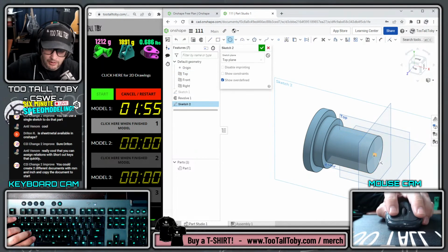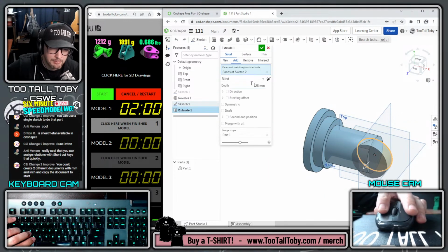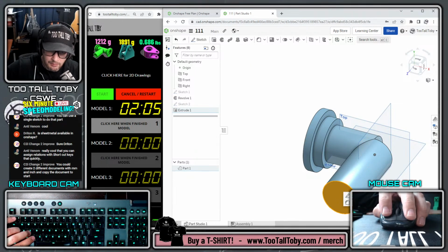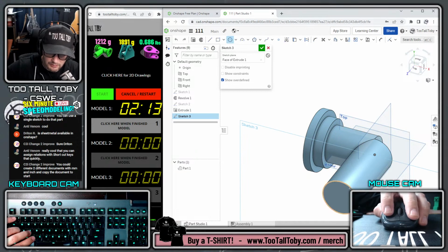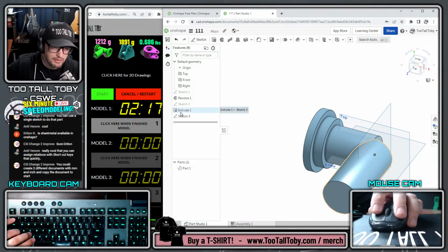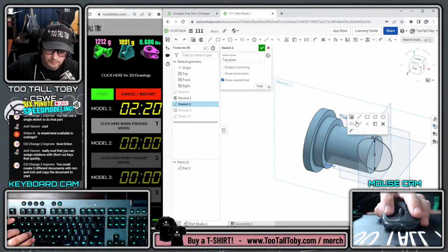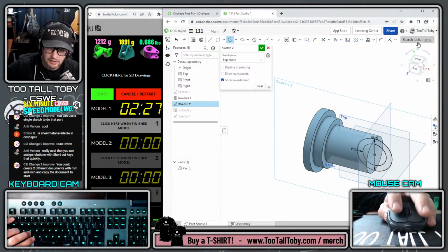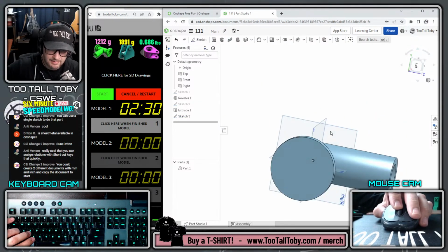We could do our circle here with our diameter 75 and then extrude that out to our depth of 160. Then there's a couple of ways we could do this one, right? We could do a cut extrude here. I wonder if that previous sketch probably should have included that other circle. So if we did this one with both circles, and that one is at 50 for the interior diameter, then that sets us up to do